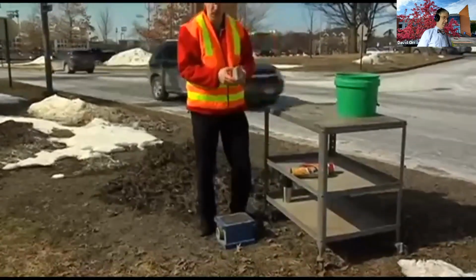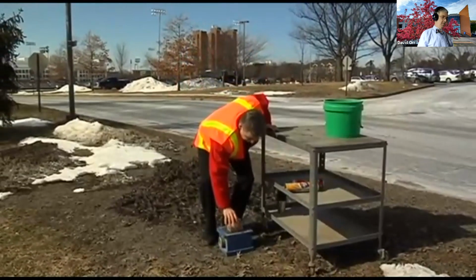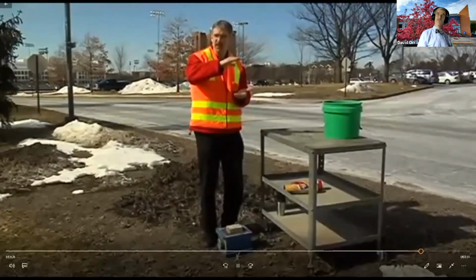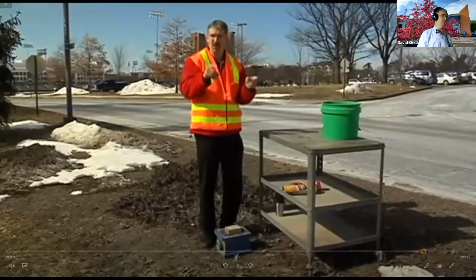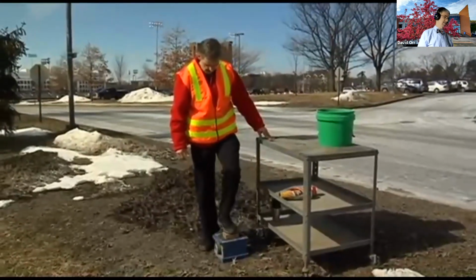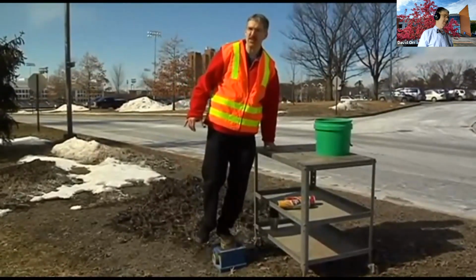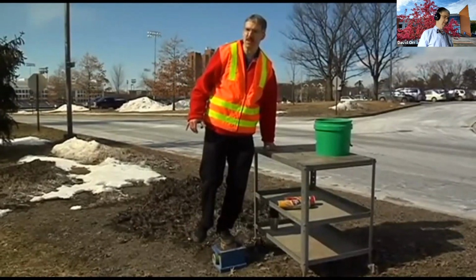I'm going to put a piece of wood. Main reason I do that is I don't want to point load it. Normally we want to have a foot of cover over any pipe that's under a roadway because it's the weight of a truck. In this case, we've only got an inch or two. And as you can see, it supports my weight just fine. No issues at all.